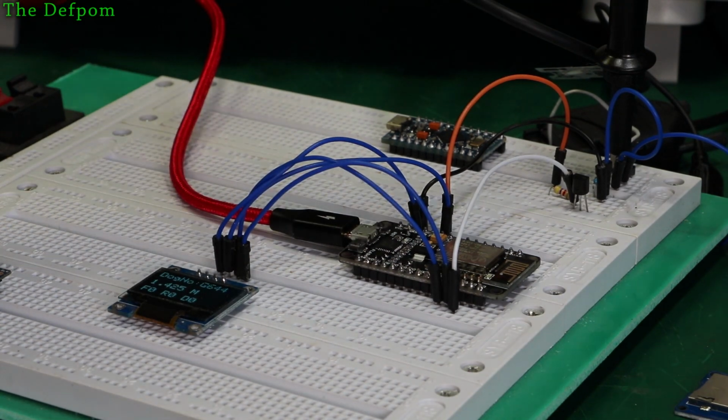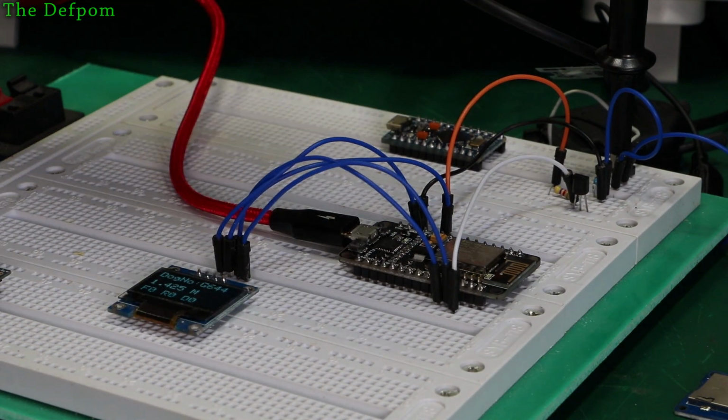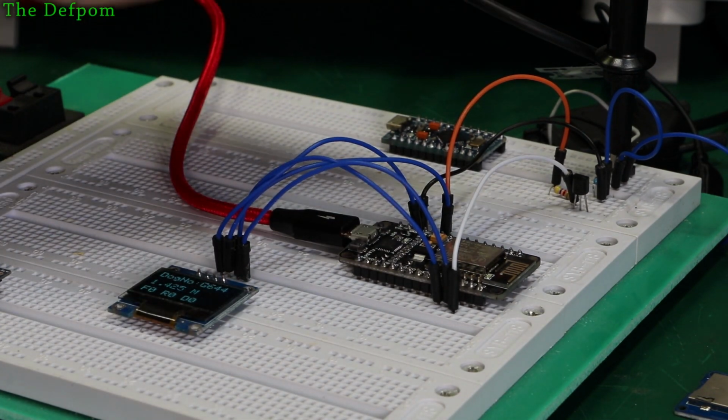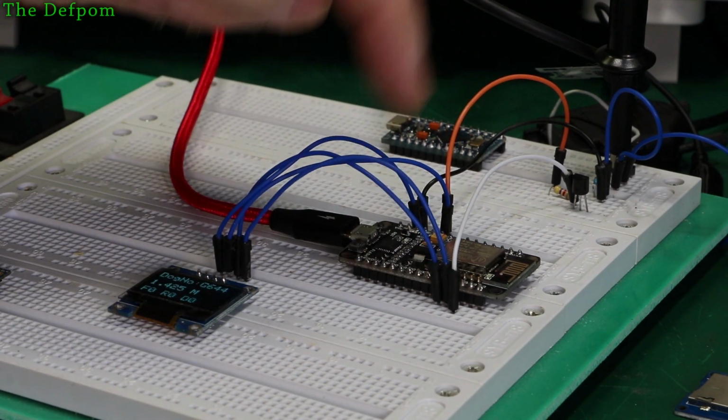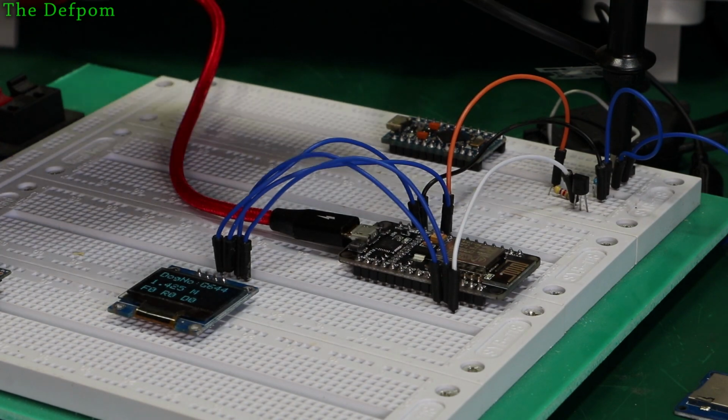There's probably some way of doing it, but it's easier to chuck a transistor and a couple of resistors in. It does dual function. One is it's inverting the signal, and the second is it's also level shifting, because it's only one-way communication. It's only out of the device into these. These are only reading it, so it's a TX line coming in.